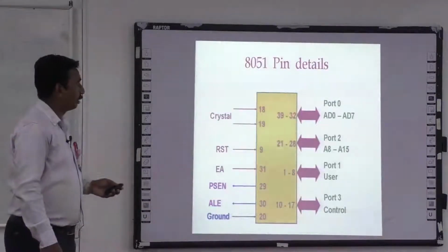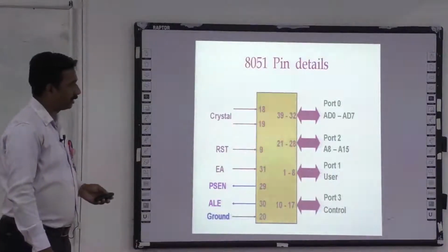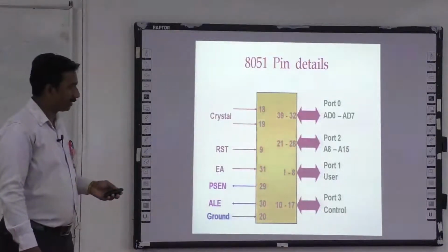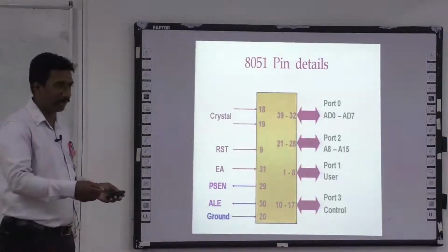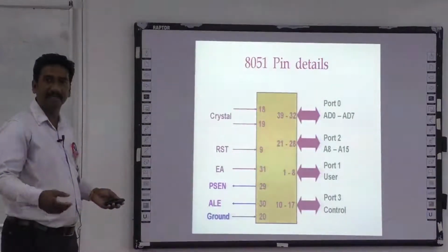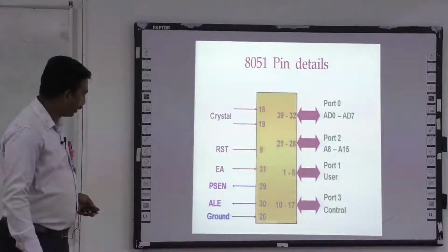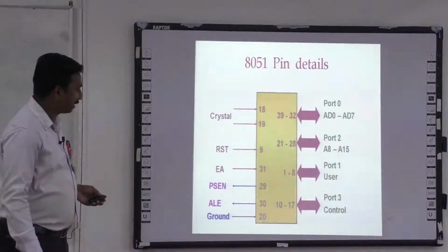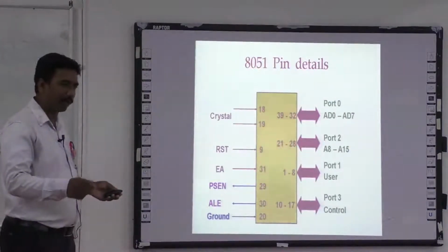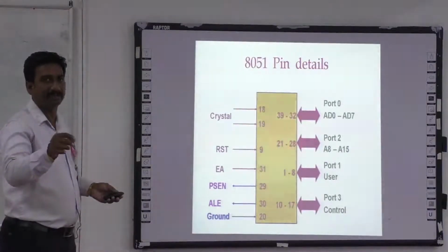And this is the pin diagram of 8051, and basically the IC has pins which are assigned as input and output pins, and we can connect whatever input, like solar panel signals, and we can take outputs such as motor, LED, LCD, 7-segment displays. These are the outputs, and we can give the supply and the ground, and the reset pin is there. If a problem occurs we can press the reset button, or for any program start, the chip will initialize with the reset button.